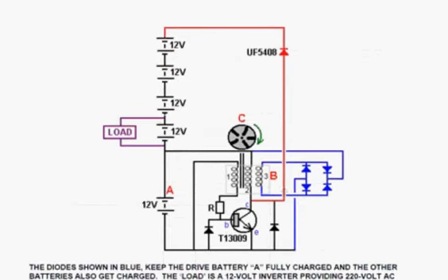Now, he started off with this circuit. He built a rotor, and in the rotor he put magnets, and the magnets spin round past a coil which has got a metal core. As it goes past, it powers the coils. It feeds, like the joule thief, the current to the base of the transistor, which drops the resistance between the collector and emitter to 0, which drives a strong current through coil number 2, and powers up coil number 3 as well.